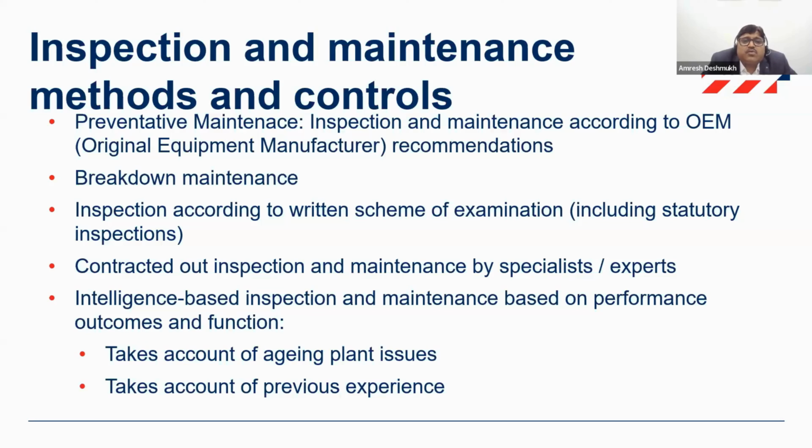While doing inspection, also take a few other things into consideration. See to it that the aging of the assets is thought of. If there are assets which are aging, you also need to have a replacement cycle in place. If you are going to put it back to use even after the useful life, ensure that necessary predictive maintenance is taken care of. You have those outcomes that if it's been put to use, it's been done post necessary testing and validation from the quality front as well. The quality has to approve that this equipment is good to use even after its lifetime.